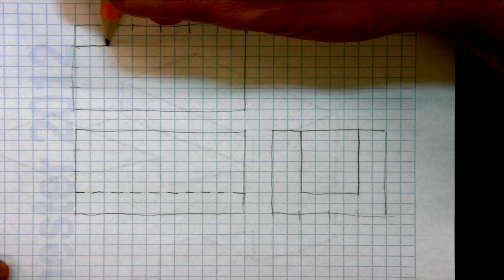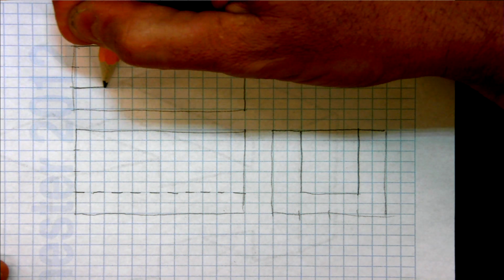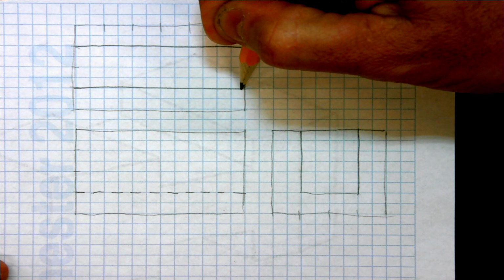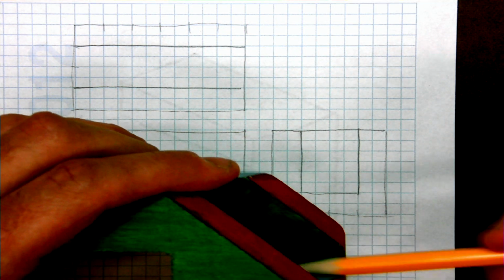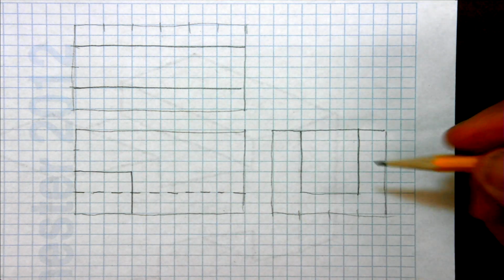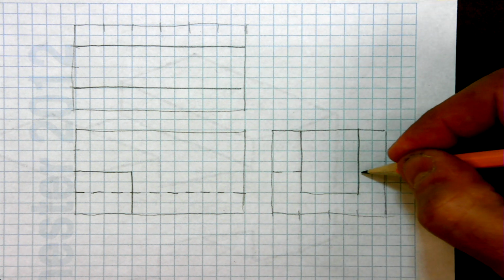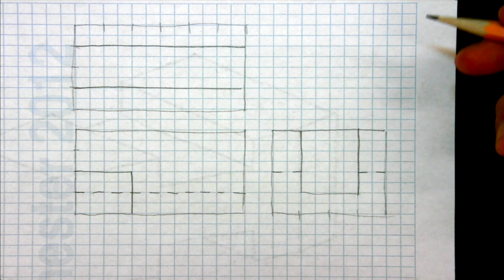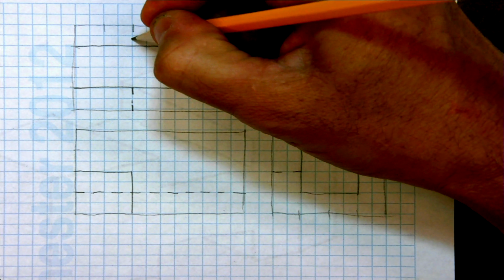So I'm going to go across here, because it goes all the way from the right-hand side to the left-hand side, and from the left-hand side to the right-hand side. So now it's just as if this thing's a U, just cut right out of there. You cannot see that edge, that horizontal plane, but it is there. So then let's go through here and cut out this part of it, right in here. And now with that cut out, you know there's got to be a dash line here and here, a dash line there and there. With that being cut out here, it's got to be a dash line here and here, there and there.